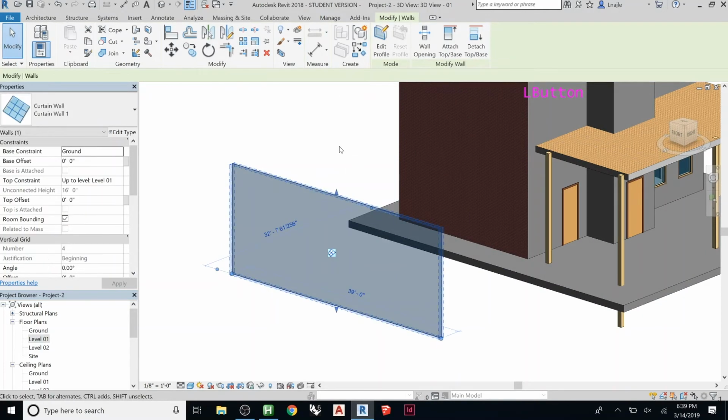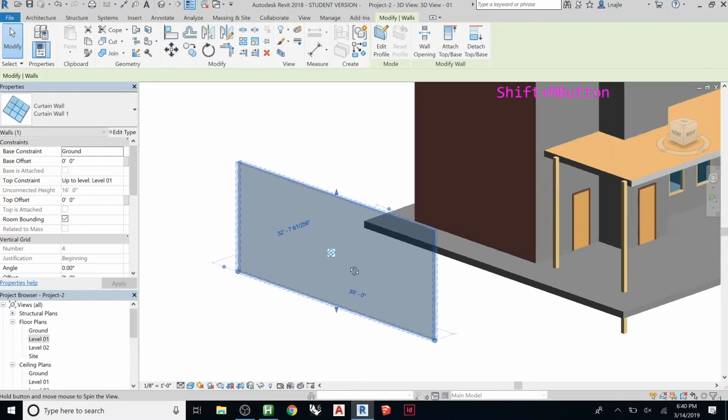So this is really helpful because if you're trying to do a big curtain wall, or an intricate kind of L-shaped wall or any sort of shape, we can do that with the curtain wall. And a lot of systems, like a metal panel, or I've seen even different sorts of door systems, they'll make them out of a curtain wall. So even though it's not a real curtain wall in real life, the way you model in Revit is more closely related to that kind of system, so they make the family work as a curtain wall.